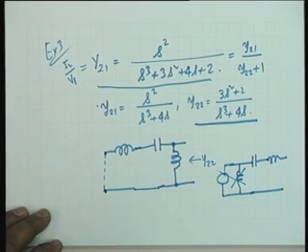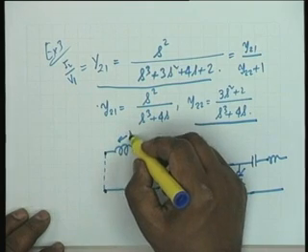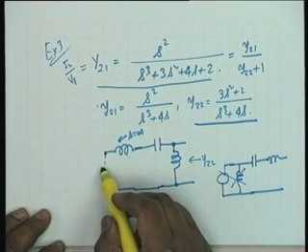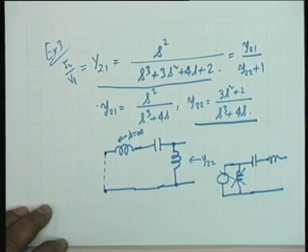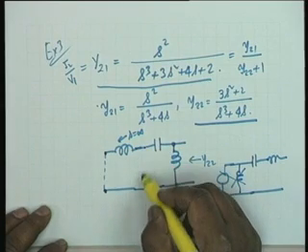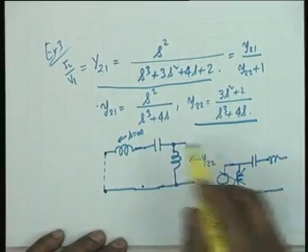So how did we get the second inductor? Oh, this is to take care of the transmission zero at s equal to infinity. Third transmission zero. So there is a voltage generator and this inductor in series will cause a transmission zero. So can we interchange the parallel inductor and the capacitor? Can we interchange this and this? That means can we have an inductor here? Yes. No. That's an interesting question.